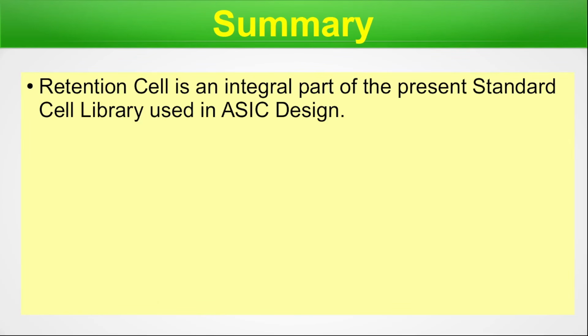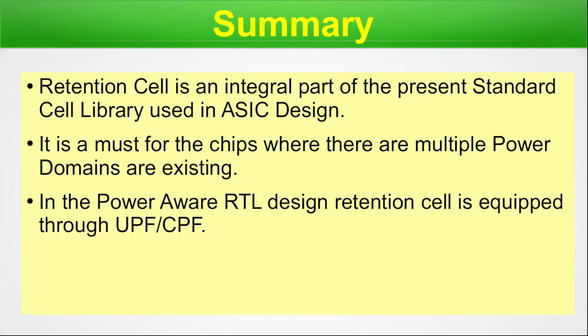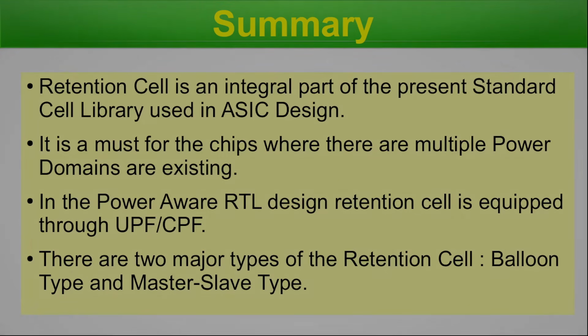Summary. Retention cell is an integral part of the present standard cell library and used in ASIC design today. It is a must for chips where multiple power domains exist. In the power-aware RTL design, retention cell is equipped to the UPF or CPF description. There are two major types of retention cell known as balloon type and master-slave type. So we have summarized our entire discussion here. We are done with this particular slide.